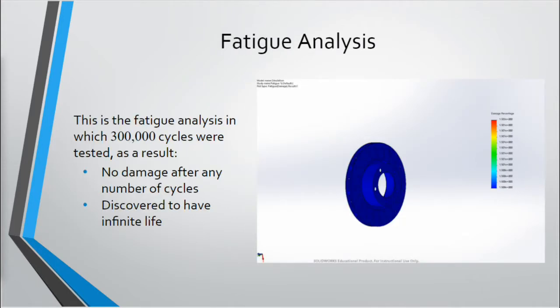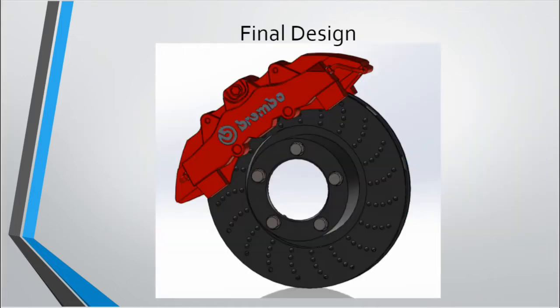After doing the fatigue analysis, even at 300,000 cycles, there was no damage on the component. It was found that the disc brake had infinite life under those tested static loads. Here's the final design for our disc brake. There's nothing out of the ordinary in comparison to the real-world designs of disc brakes.